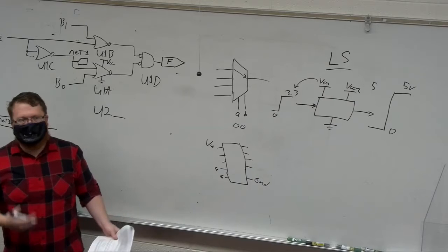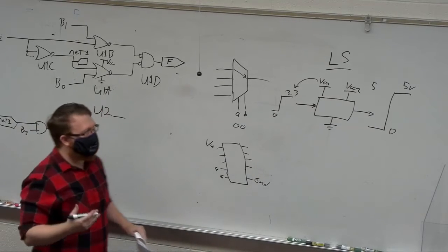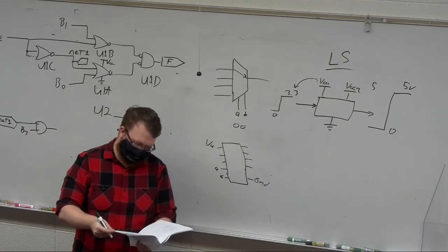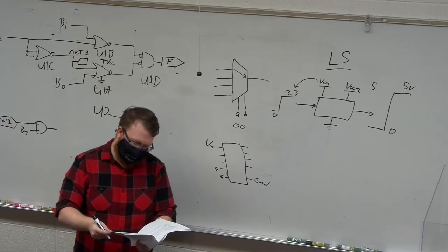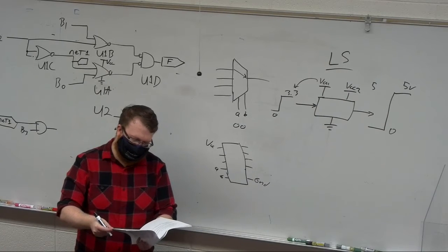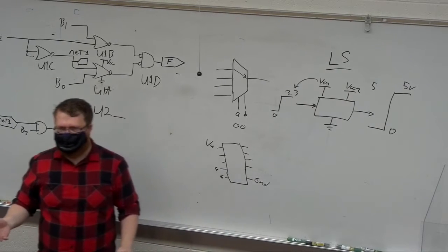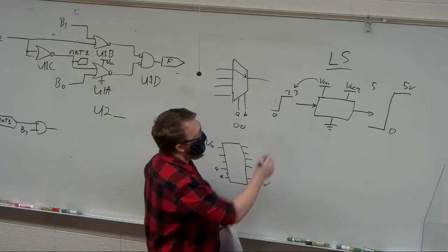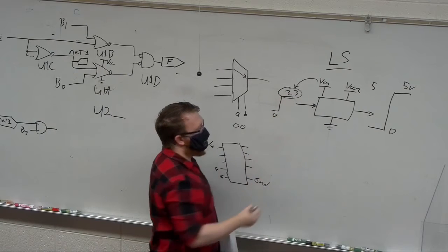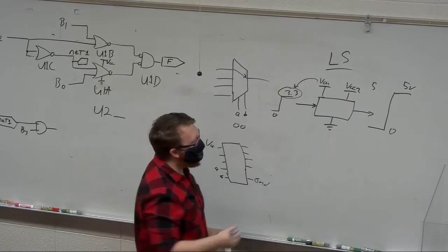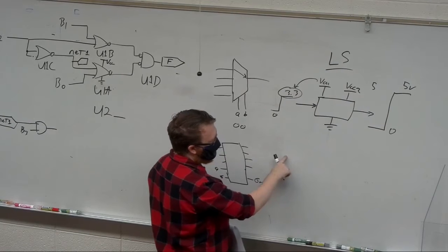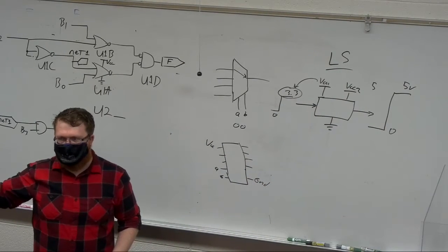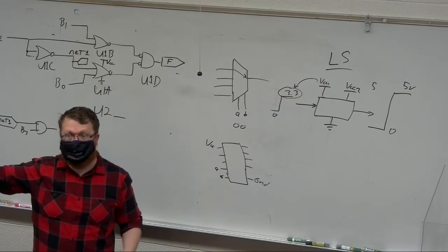That's generally how you would transition them. But you may notice that in some of these logic families, you can actually just plug them together. So like the LS and LV, the low power Schottky and low voltage, they're slightly different logic families. But even though that's true, a lot of the times the 3.3 input, say, so if I'm inputting a 3.3 volt into a 5 volt, that 5 volt may swap over at 1 volt.